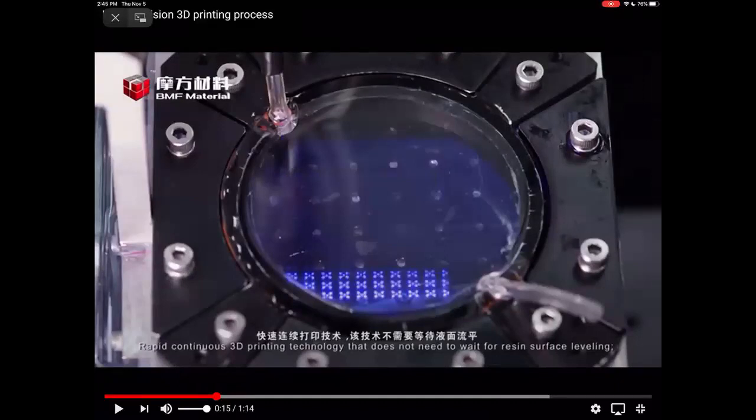And so in regular stereolithography, you have some focusing lenses in order to get the right focal plane and everything else. But microstereolithography will tend to be done through one of these zoom lenses, so you can get very small feature sizes. Of course, you can only print very small things in microstereolithography, but this is worth thinking about, how you get these small structures.